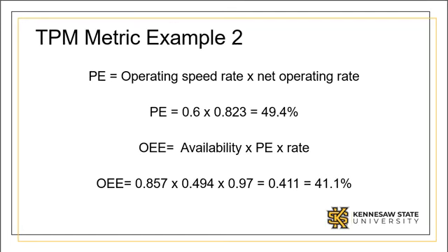This is actually a very low OEE. Companies that have highly mastered the principles of TPM perform at OEEs of at least 85%. Because the OEE calculation consists of 3 efficiencies in series, this leaves very little room for error. Even aiming for availability, PE, and quality rate at or near 95%, we barely deliver a TPM process at 85%.